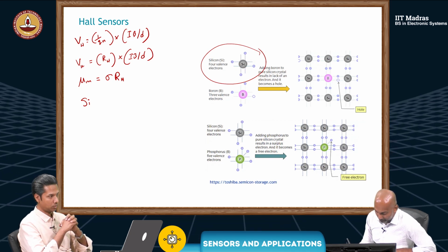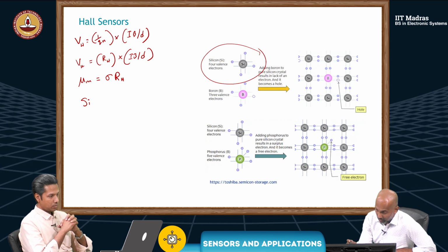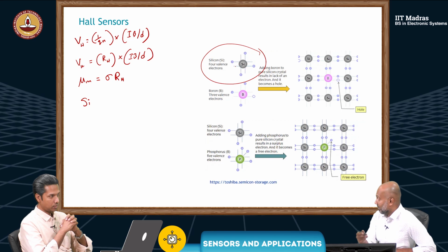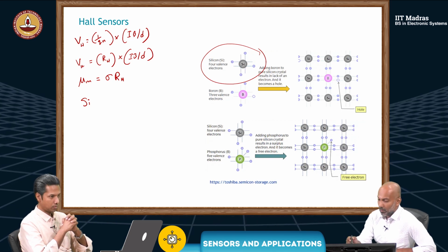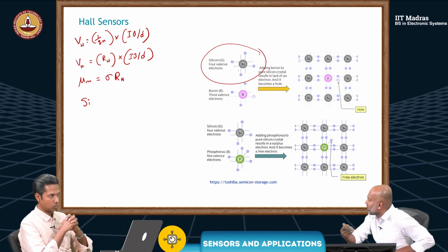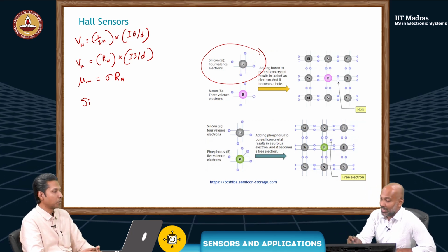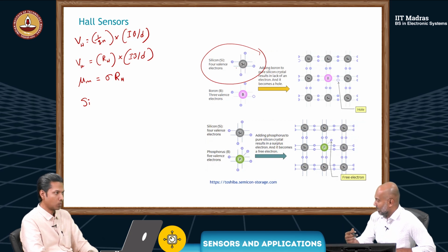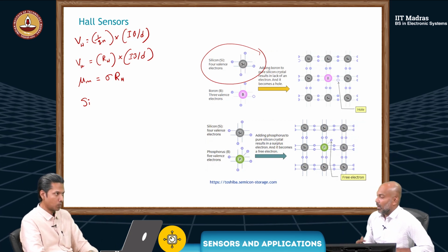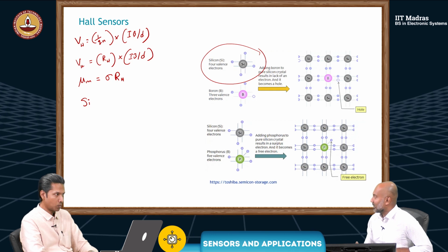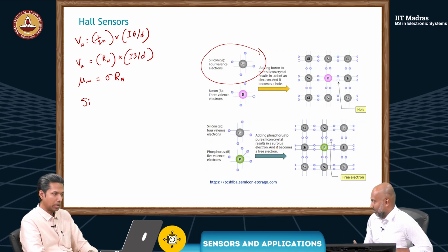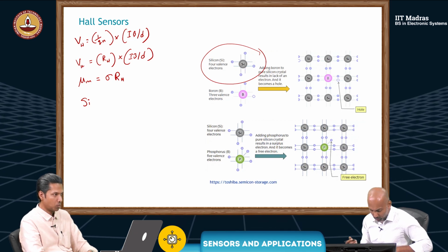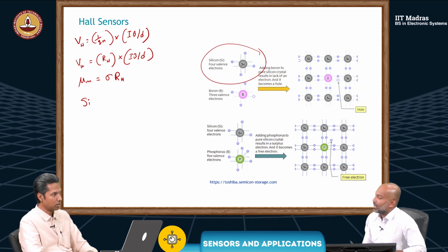Now, however, the problem with silicon is, okay, it has a lower charge density than a conductor, but you should still have some free electrons, right? Correct. But for these electrons to break from the covalent bond, the thermal energy that's required is generally much higher than room temperature. Yeah. Okay. So good, but not great. So what do we do? You will dope it. Exactly.